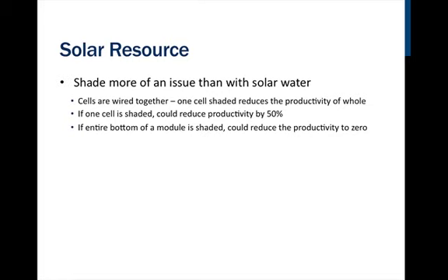For this reason, and because a PV system is more complex, it is vitally important to get a site assessment done by a professional. A site assessor will look at the efficiency measures that could be taken into account. A PV site assessor is trained to decipher the solar window at your site, your specific electrical needs, and possible shading considerations. The site assessor can advise the right type and size of system for your site determined by your budget, your wants, and your site's features.